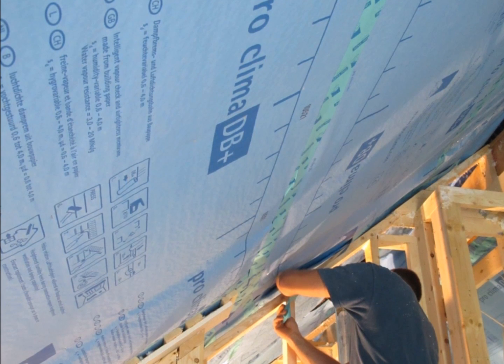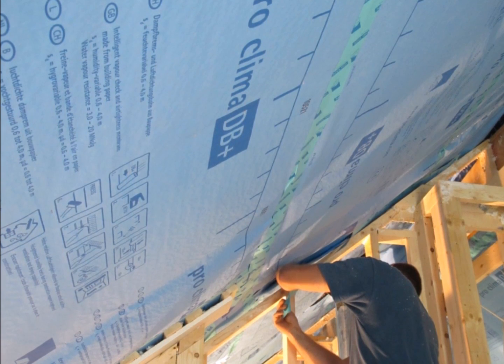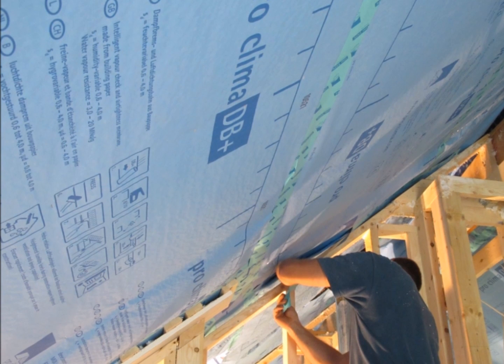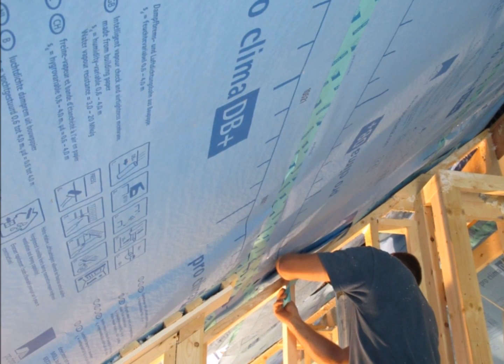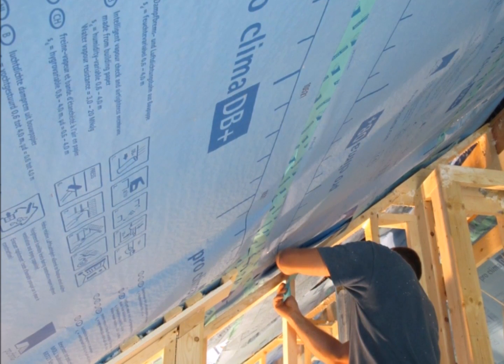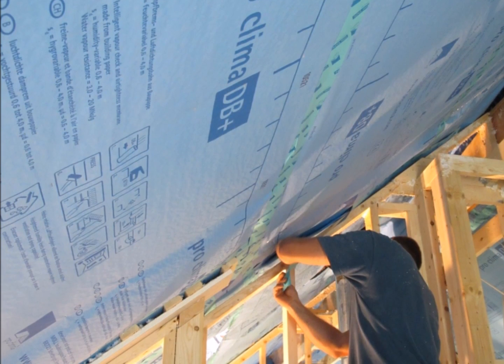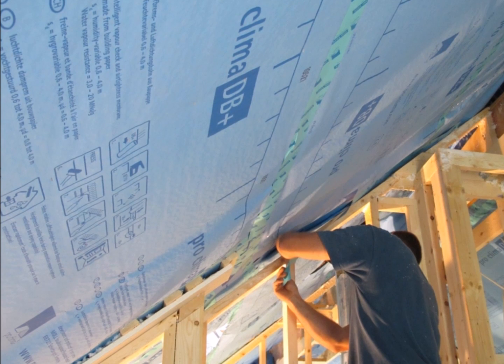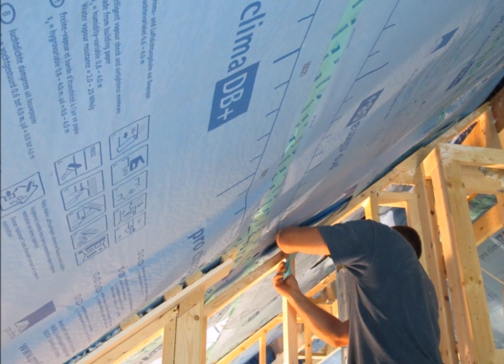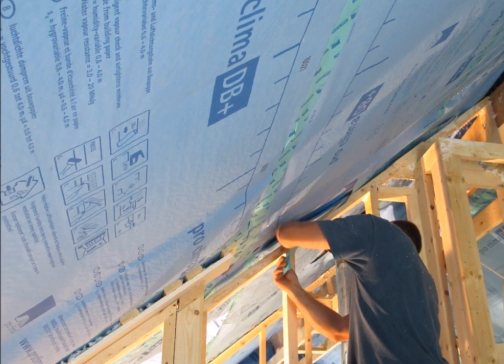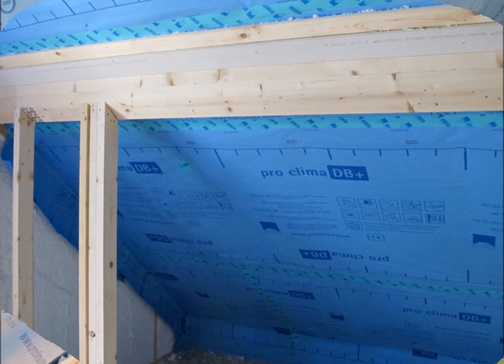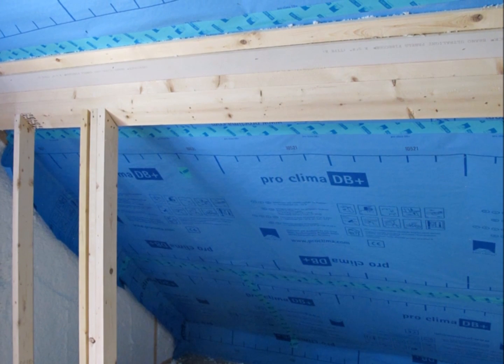The roof to the exterior wall must allow water to properly shed, as well as allow proper ventilation for the attic area and provide a proper seal against water intrusion into the exterior wall covering. These details are often lost between the work of the framers, roofers, as well as the masons. If not properly coordinated, a latent defect is created.